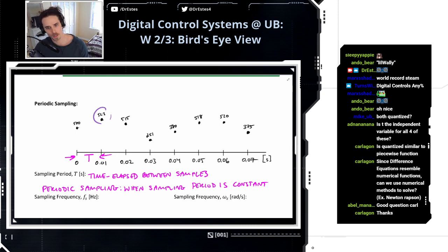So I'll show you a code on an Arduino in a couple minutes where I'm gathering data from an accelerometer. And what I do is I build a timer into the script so that I can regulate this sampling period. If you just let an Arduino loop run on its own and gather data from a sensor, there's no guarantee that the samples will be evenly spaced.